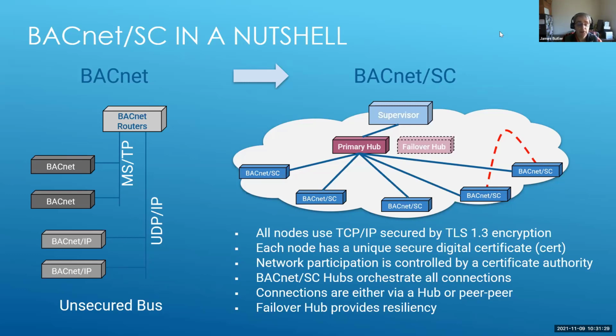But the industry wanted more, so BACnet Secure Connect was developed. And the key point about BACnet Secure Connect is that it leverages modern information technology to provide cybersecurity in a way that BACnet IP does not.